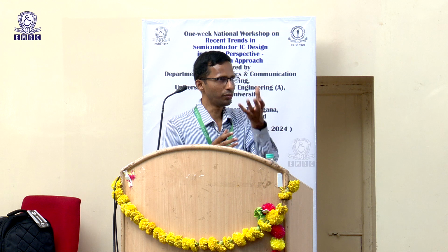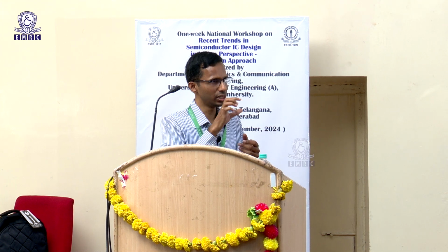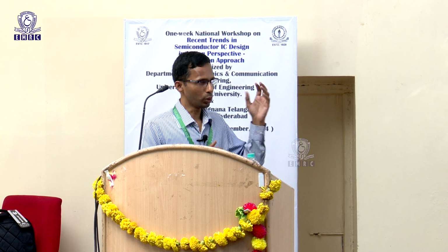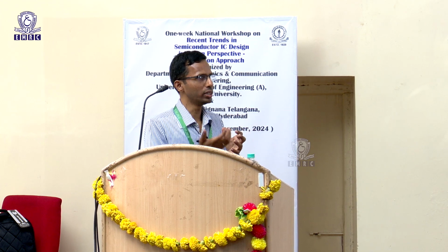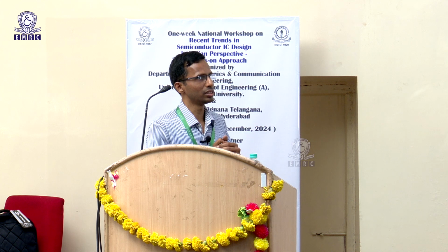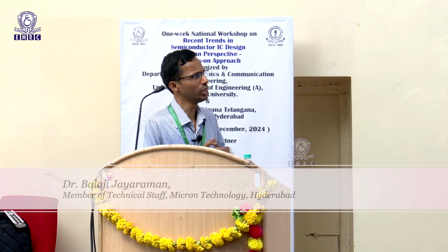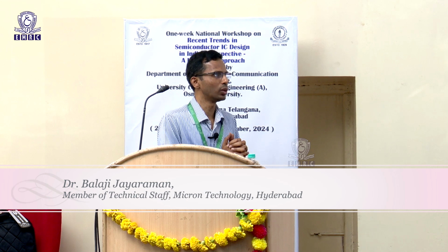So you need that FIFO built in. All that FIFO is your digital logic. Your high speed interface is digital logic. Your row address and column address decoding is digital logic, your command address decoding is digital logic, your mode registers are digital, and some amount of digital goes into your delay locked loop as well. So there's a lot of digital that goes into the system.